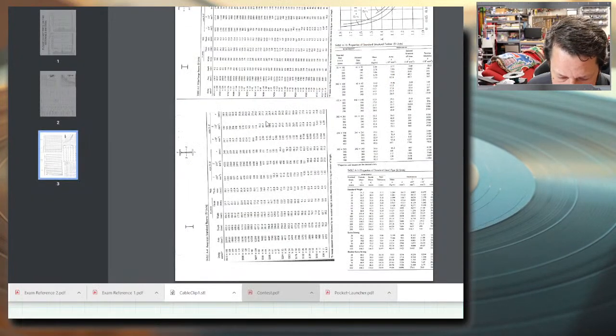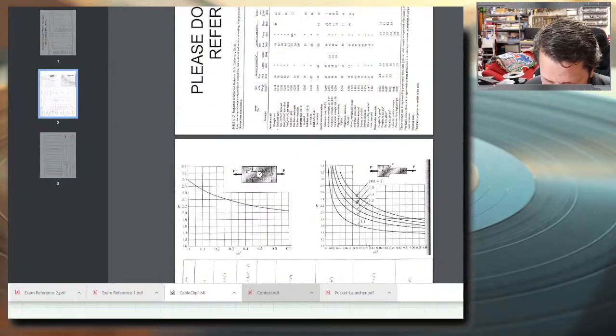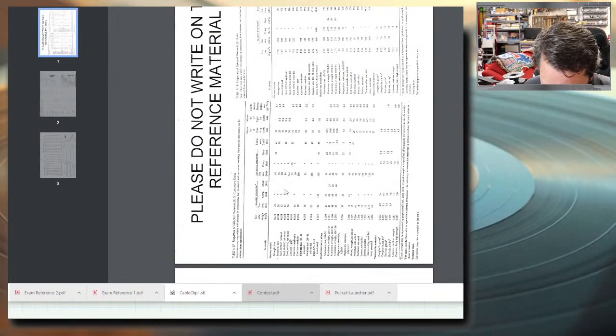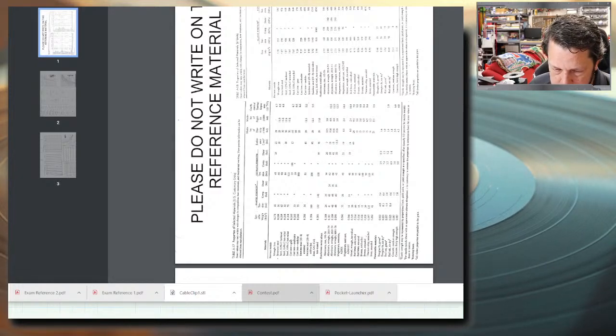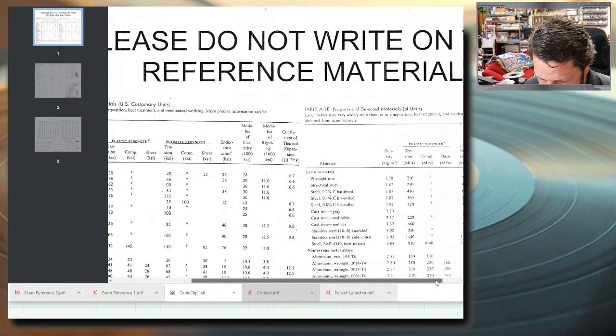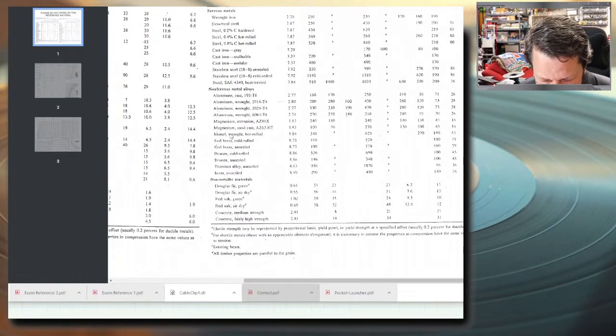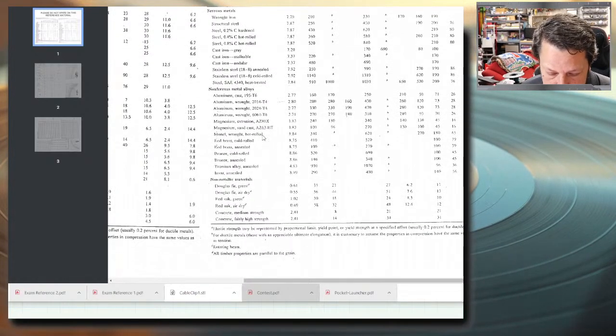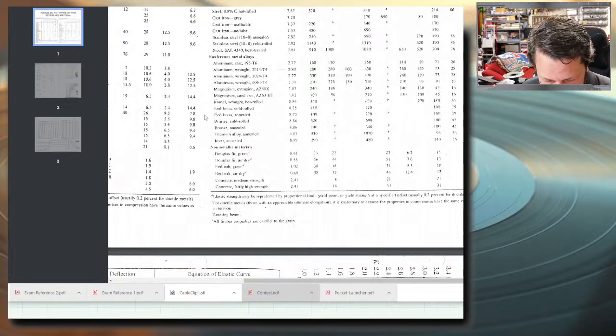Do we still have, yeah, we still have these. Let's see if I can find it in here somewhere. These are the KSI units, so this will work, but we need to rotate it. Not that way. There we go. There's megapascals. We need these units. So everything else was in millimeters, so we need those. Let's zoom in some on it so we can get a chance at seeing this thing. Hot rolled mono, it's also wrought on here, but that's the same thing. 180 gigapascals. 180 gigapascals is our modulus of elasticity.